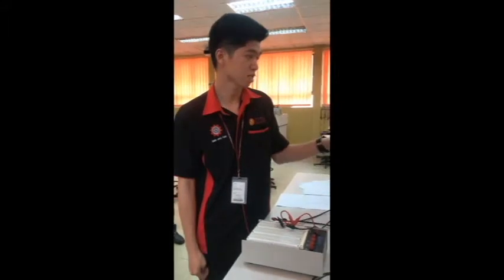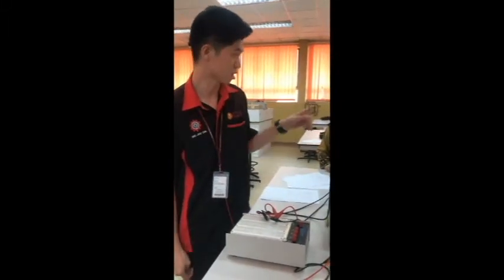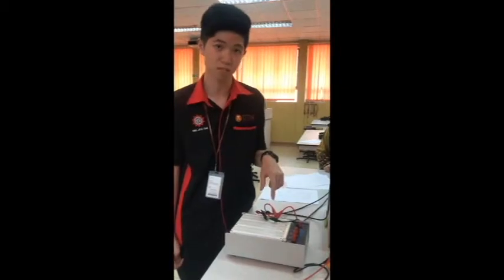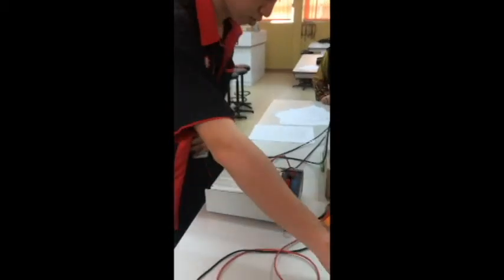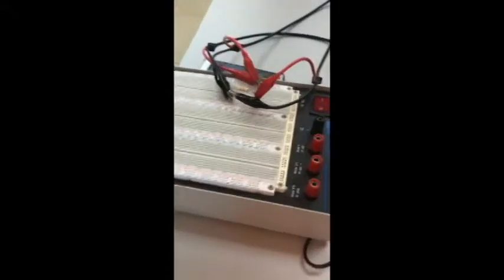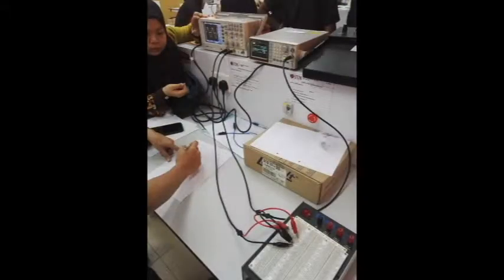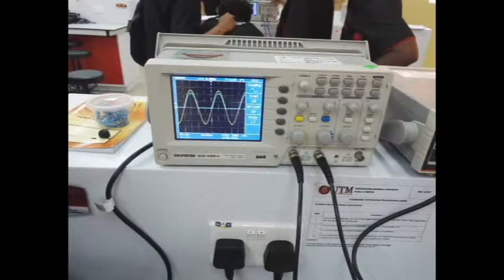Then we will be connecting the function generator wires and the oscilloscope wires to the circuit board. This is how the AC supply connected with the oscilloscope and the circuit that consists of the Si diode and the resistor looks like. Through the oscilloscope, we can obtain two different sine graphs by comparing output 1 and output 2. We can see that the graph only shows positive and it's slightly lower than the output 1 V peak.